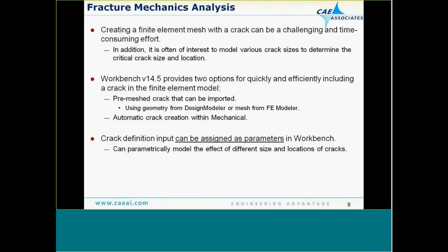So what I'm going to show you today is that Workbench in 14.5 in Mechanical provides a couple of options that allow you to put a crack in your mesh. The two methods are either coming in already with your geometry or mesh already with a crack in it, and you're just going to identify it in Workbench and tell Mechanical, look, this is where the crack is, use this crack and let's calculate K1.